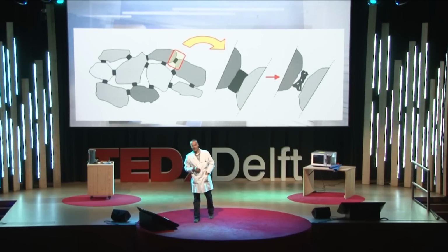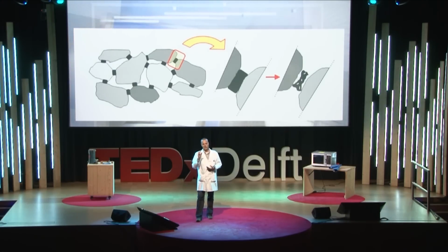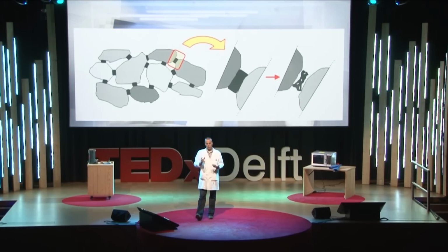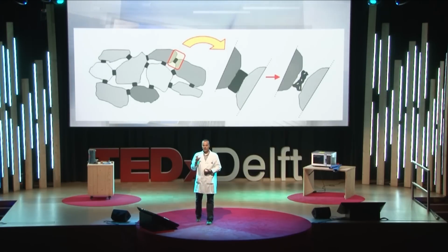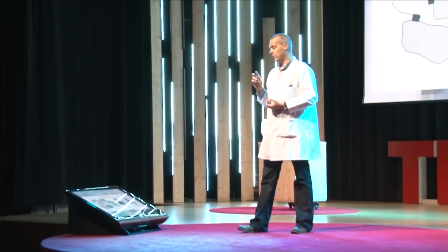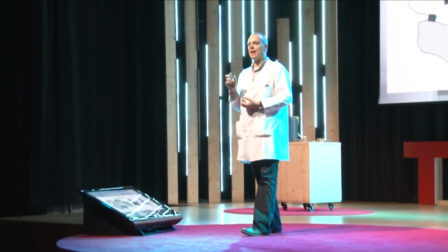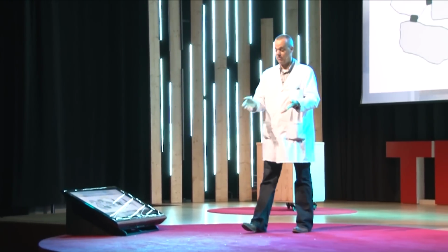Here you see actually how the damage appears in this material. It's a porous asphalt, like I said, so you have only a small amount of binder between the stones. And this binder, due to weathering, due to UV light, due to oxidation, this bitumen, the glue between the aggregates, is going to shrink. And if it shrinks, it gets micro cracks and it delaminates from the aggregates. And then if you drive over the road, you take out the aggregates, what we just saw here.